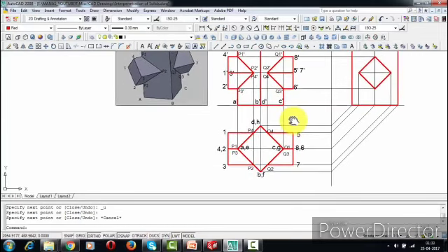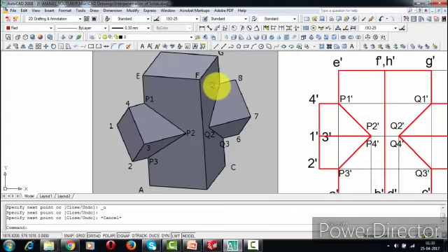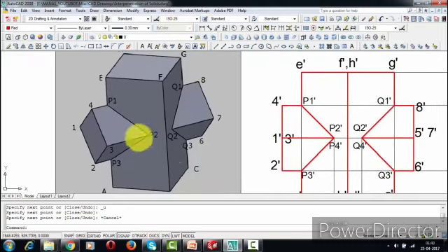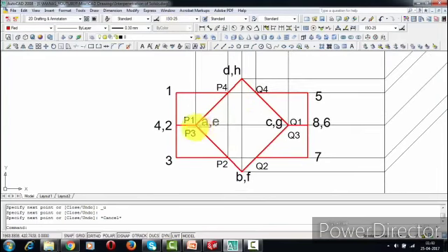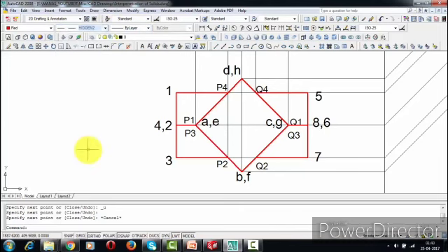Okay, we're almost done, with a few modifications yet to be carried out in the form of hidden lines. Okay, now a small portion from P1 to Q1 of this edge 48. It's not going to be visible, but we have to give it some respect in the form of creating a hidden line. From P1 to Q1, we've got to make this line. So right now I'm going to be erasing this portion, and I'm going to be using a lighter line, a red color line in fact, but a different sort of line, a hidden one.